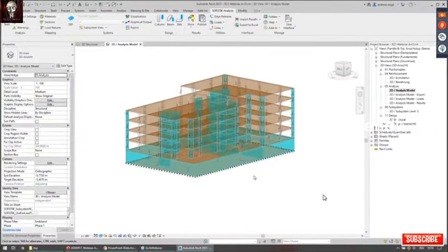So this is essentially, or probably, the first step which is being done when you get a model from someone else to check for the analytical consistencies using this command. Yeah, and once you did this, you can start adding attributes to the elements. So for adding attributes, we provide a specific structural properties pane, which can be activated here.